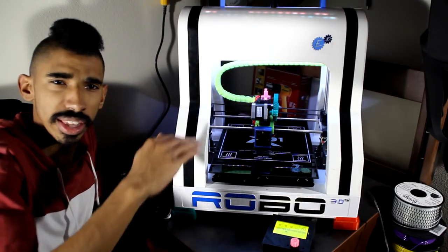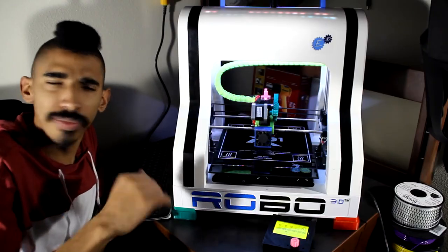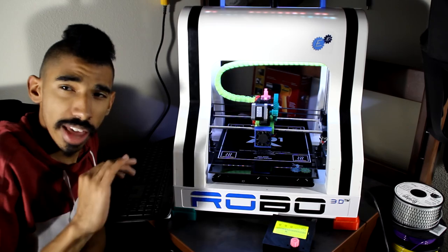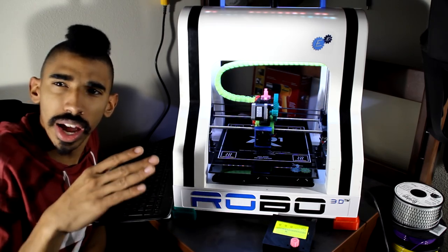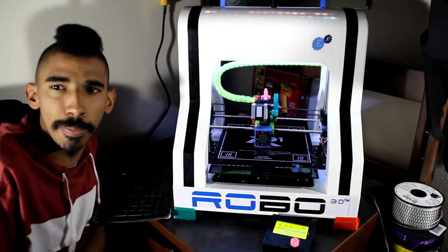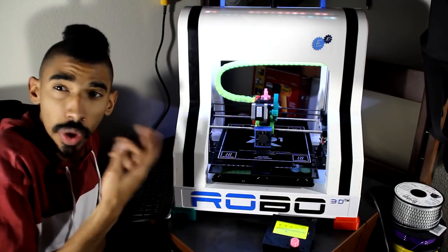So you want the extruder low to the bed, you want your fans kicking at 100%, and then you run your PID tune. By doing that, you'll give the printer a good estimate on how fast the fans will decrease the temperature, and it'll run the PID tune better.